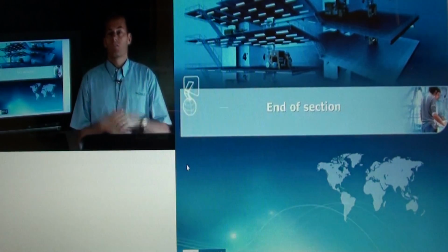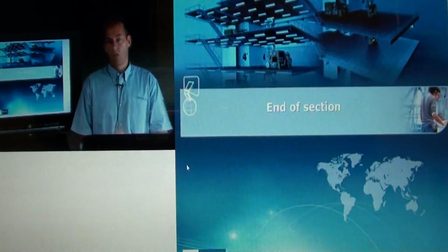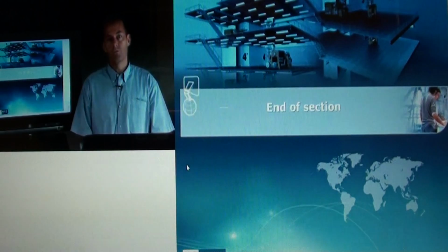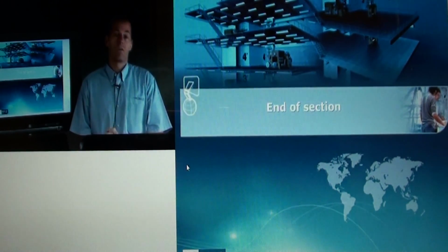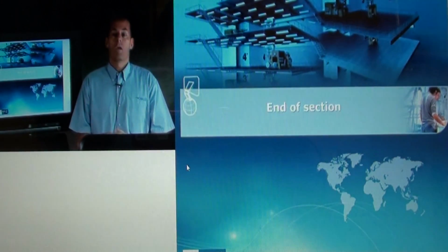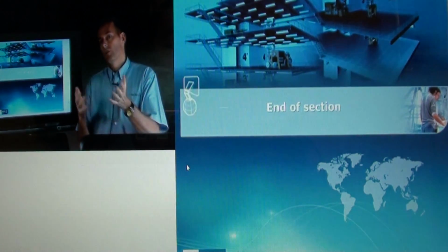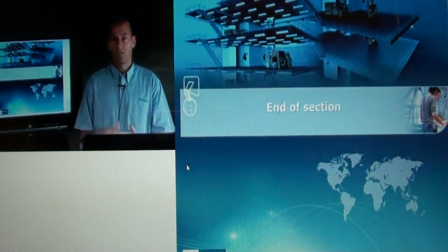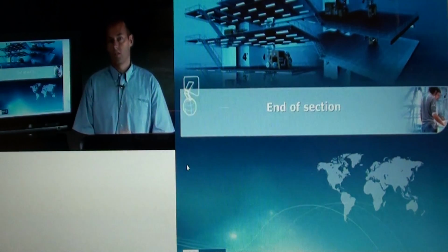Anyway, there are some tips to do with spectrum analysis and time waveform analysis. I hope they were useful. They are both very useful techniques with detecting bearing faults, and we will separately look at demodulation, peak view, shock pulse and those techniques as well.